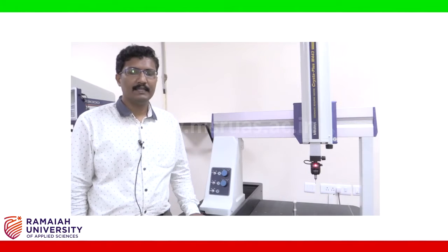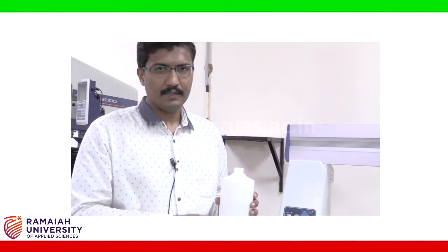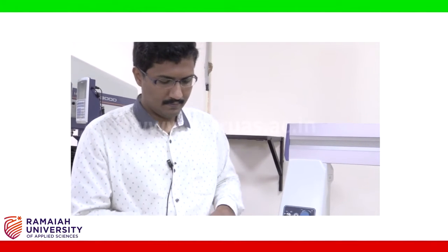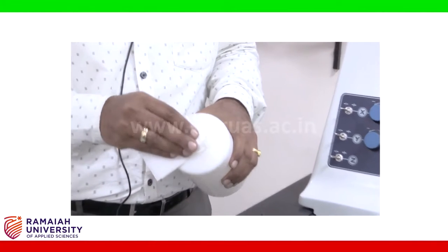We need to clean the X, Y and Z axes before starting the measurements. We are using isopropyl alcohol, or IPA solution, to clean the axes of the CMM machine. You can see the isopropyl alcohol in this plastic container and a soft tissue. So now I have the IPA solution on the soft tissue. I am using this for cleaning the X, Y and Z axes.